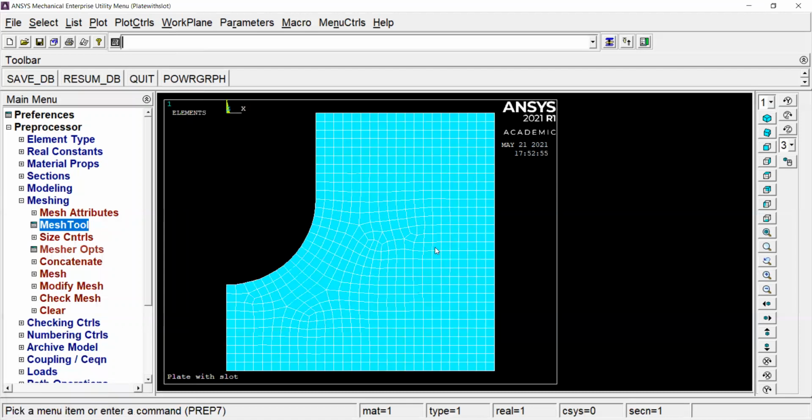Now you can see it's broken up our element into all of these little grid squares. Right, and that is a mesh. This is a 2D mesh. Before we were using one-dimensional meshes. When we did our beams, those were one-dimensional meshes. This is a two-dimensional mesh. We have an X and Y component for each of those little squares.